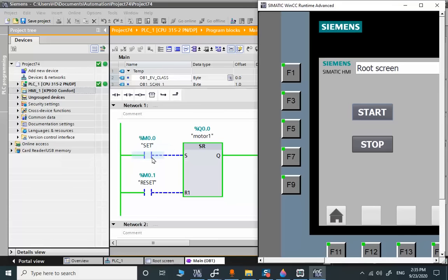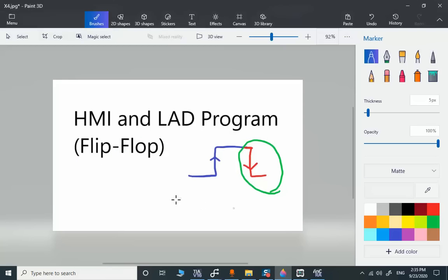We have very short pulse in M00 and very short pulse in M01. So it's possible to start and stop a drive or any binary signal from the HMI by using this method. We only set the command signals in HMI and reset them in the user program. It's a very simple approach.